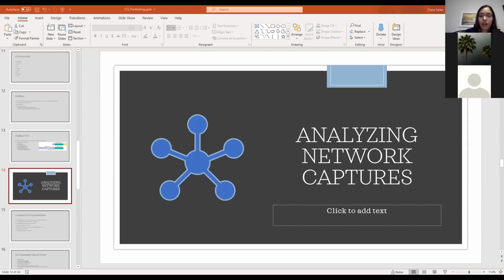And then this is reading from holding registers. So you can see these are UINT 16 registers. You can see the register value is 9, and that's from register 5. From register 6, you can see a value of 24. So this is just showing the process of querying and then responding back and forth between an engineering workstation and a PLC.